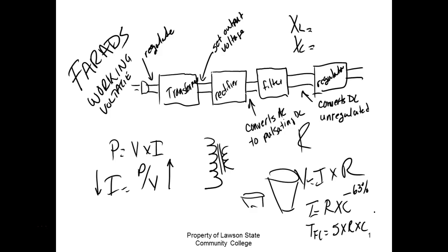But when we charge this guy right here, the only resistance it sees is the forward bias resistance of the diode, which is almost nothing, and then the resistance of the transformer, which is almost nothing. It's some, but we're talking about maybe 20, 30 ohms. So these guys are going to charge extremely fast, right? You understand? Even though they're going to be big capacitors. Huh? Because the resistance is low.